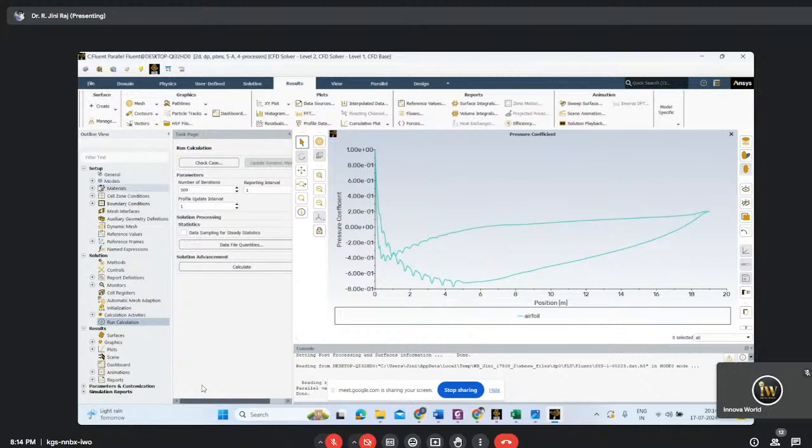And if you are giving the conditions perfectly, now I have given randomly. But if you want to give perfectly, you should study which airfoil you want to do analysis on, what type of airfoil, and what Reynolds number you want to use. Accordingly, you can give. Okay, this is how you have to do the CFD analysis. If you have any doubt, you can ask.